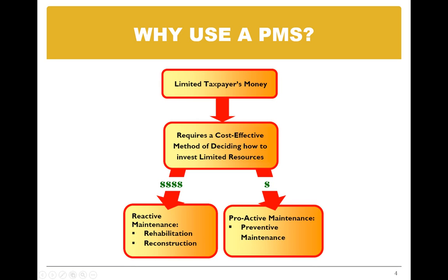And again, that was a really costly option, versus what we need to think of now, which is a cost-effective maintenance option, proactive maintenance, meaning that we're now concentrating on preventive maintenance. When I say preventive maintenance, it is a very minimal amount of maintenance activities, which is gonna keep the roadway condition at a high standard all the time. So we will not be reaching a failure mode, so we don't have to spend a lot of dollars on rehabilitation or reconstruction.